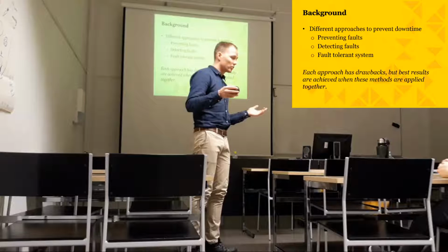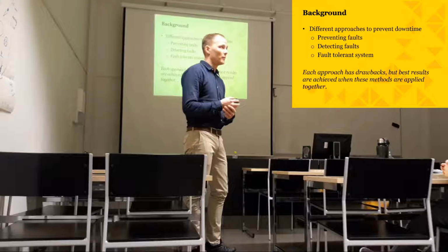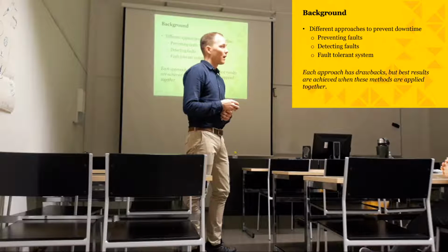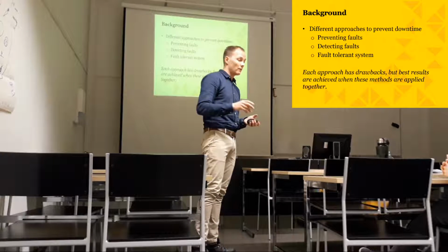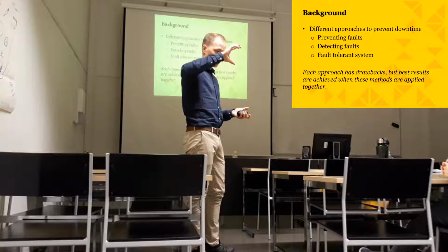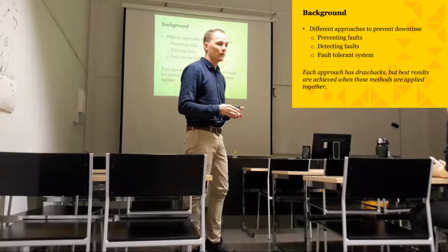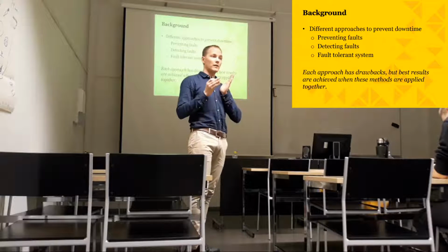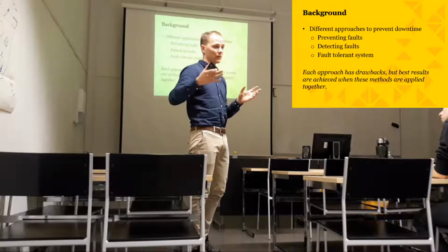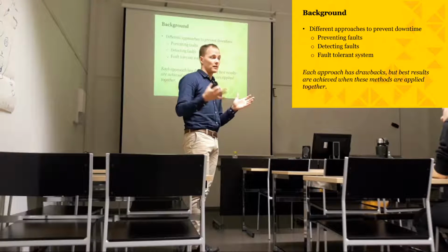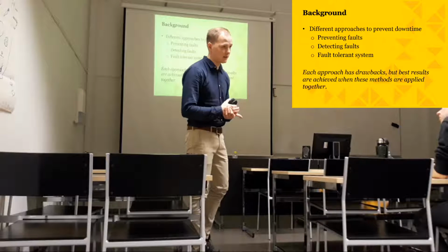Other methods could be like a gas leak detector or a fire alarm. I've often implemented in my automation designs this kind of feedback loop from the relay contacts. The relay contacts are connected back to the input of a PLC, and then we compare the start command and the actual command that comes from the coil, because these relays often fail. There are dozens and hundreds of them in an industrial plant.